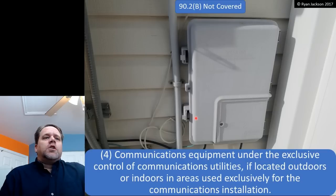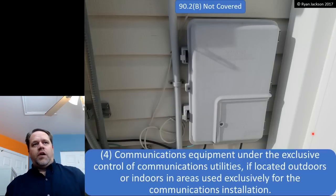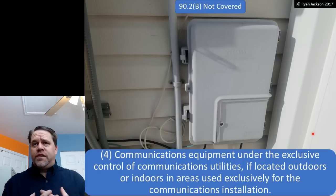Item 4, communications equipment that's under the exclusive control of communications utilities, if it's located outdoors, or if it's indoors in an area used exclusively for the communications installation. That's not covered by the NEC. What you're looking at here in the photograph is what's called a primary protector. And if I were to install that at a building, I'm not a utility. I would have to comply with the code. And the code has rules for primary protectors. 800.90, if I'm not mistaken, talks about primary protectors.